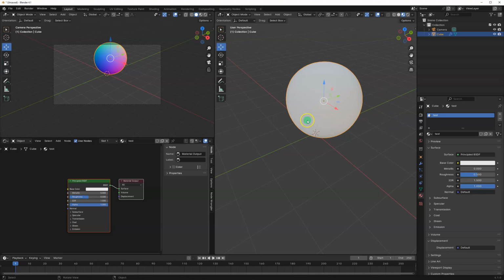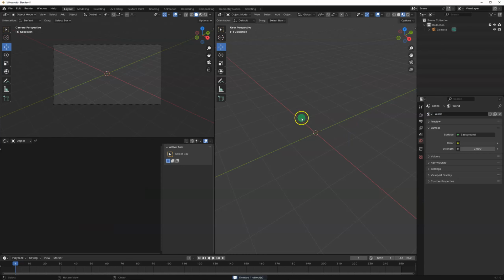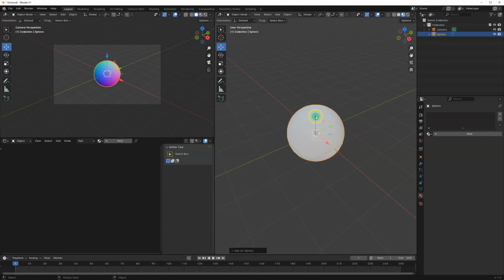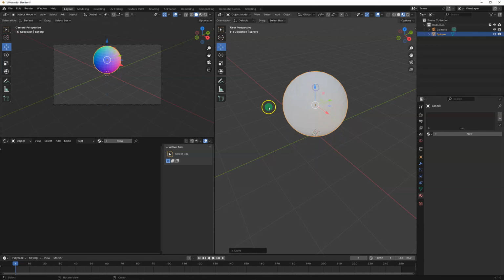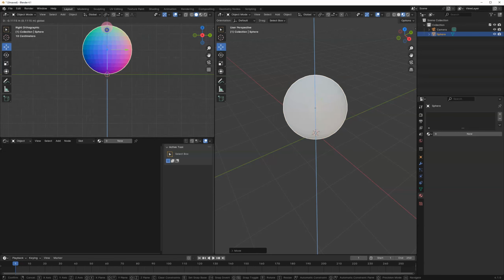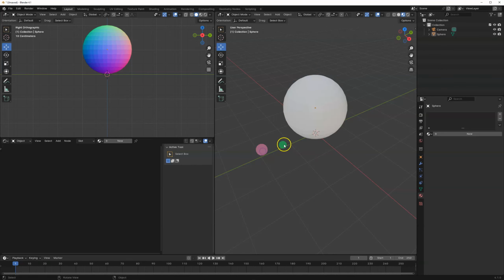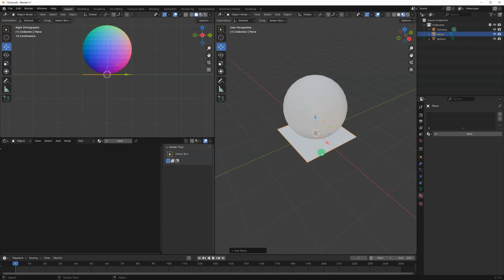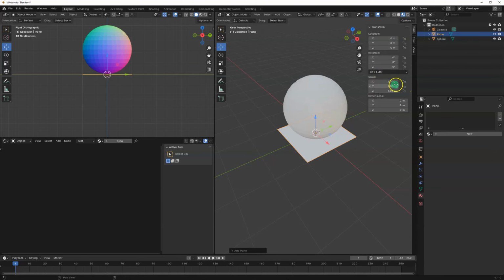The other thing we can do is we can bring in features. So I'm just going to delete that rectangle. And if I press Shift A, I can add a mesh, and in mesh I can add a cube, I can add a UV sphere. I can move this up. I could look in here from the X, and I could adjust the height, and I can also go Shift A and put in a plane, and then I'm going to press N so that we can see here.